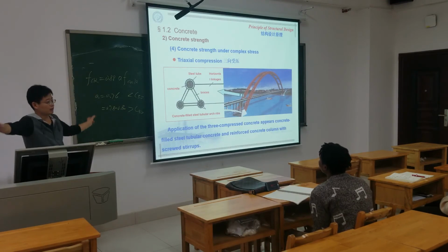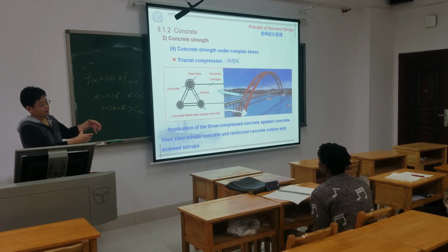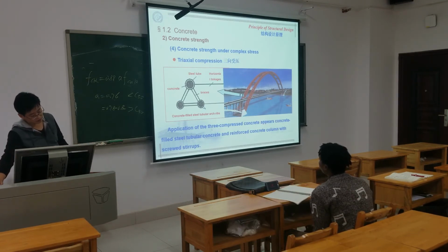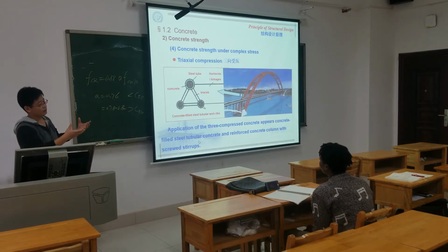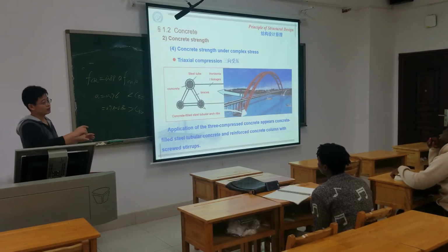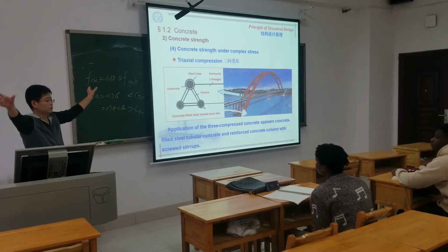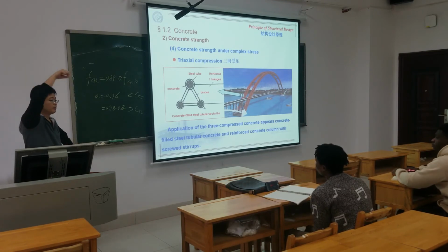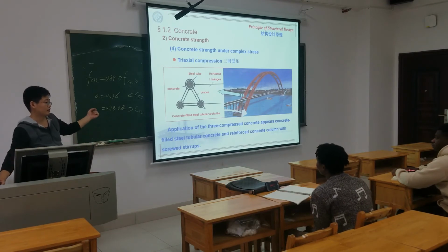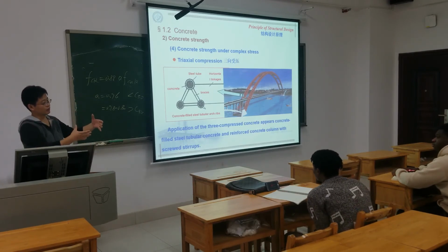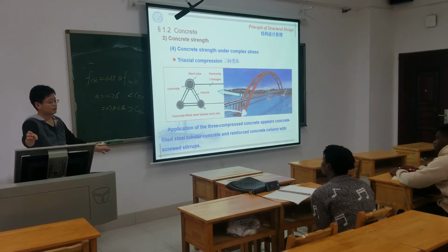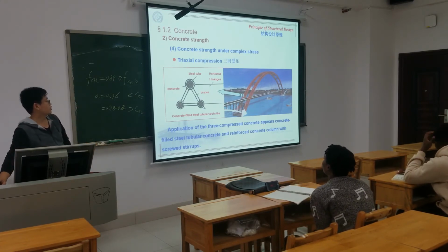But if you use an empty steel tube, it's not so heavy, and it's quite easy to build a large span. So you use the empty tube, build the ring first, and then pour the concrete inside to make a stable structure. So the weight of the concrete also makes it stable, and this weight can give advantages.